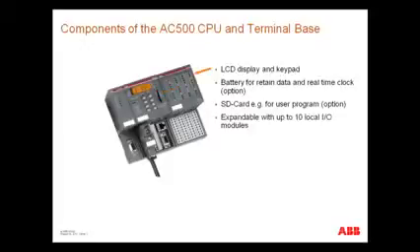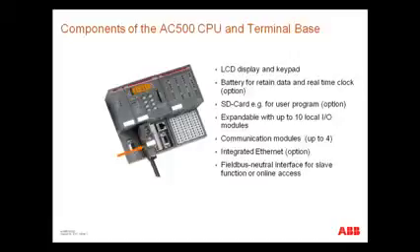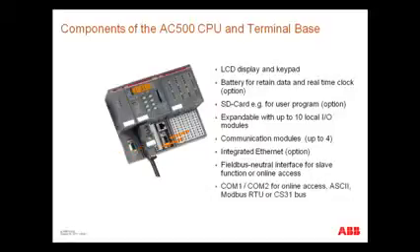Right to the controller, up to 10 I/O modules can be connected. Left to the controller, up to 4 communication modules can be mounted. The Ethernet plug on the terminal base is always present. The online access and several protocols are given for controllers equipped with onboard Ethernet. If the controller is a fieldbus slave, the fieldbus neutral interface is to be used for connection. Alternatively, it can be used for online access. 2 serial interfaces for online access and further connections are provided. Terminals for 24-volt DC power supply are provided.